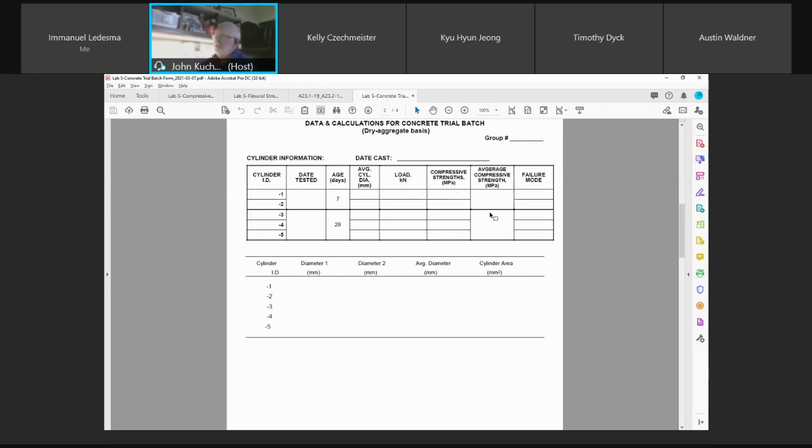And I was surprised that that's what ACI does nowadays. Before they never did, but maybe they're changing. Anyways, okay, so a test is the average of 2. And that's why you have 2 breaks at 7 and 3 at 28.